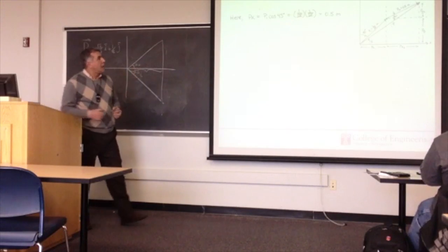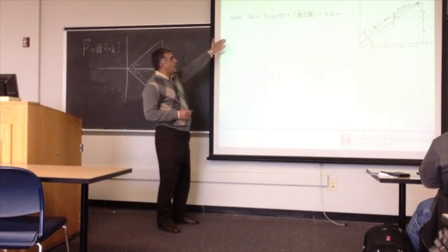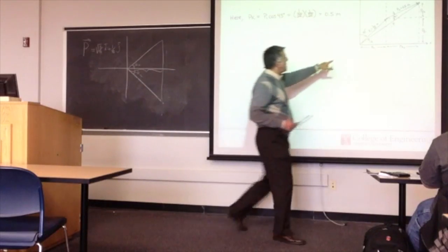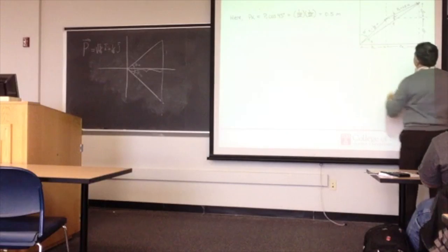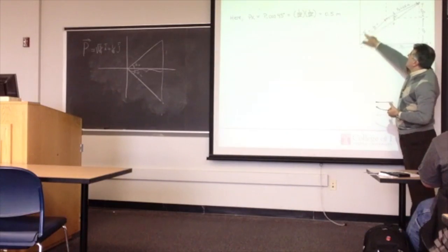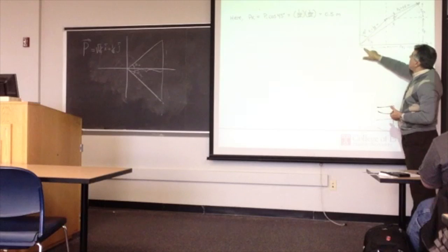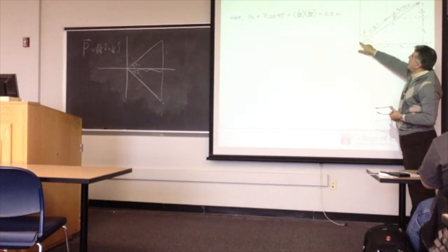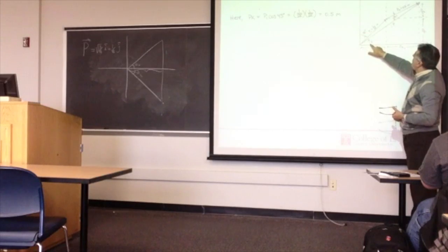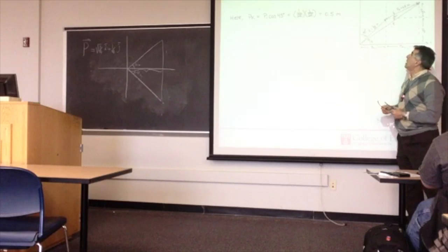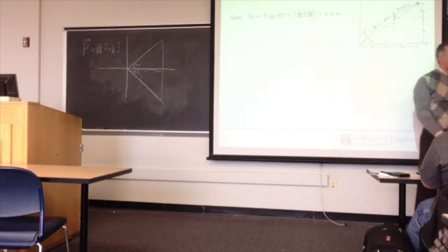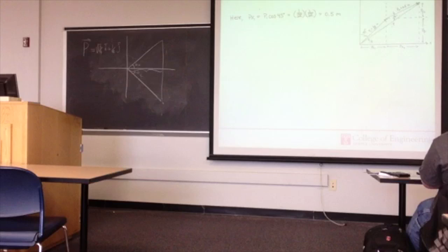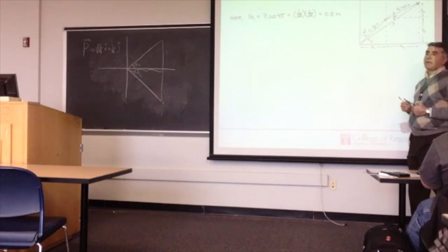So here, in this case, px1 is based on this triangle, right? This triangle is equal to P1 times cosine of 45 degrees, which was that angle. You remember? Are we using elbow down or elbow up over there? Elbow up, right. That's why theta 1 became 45.